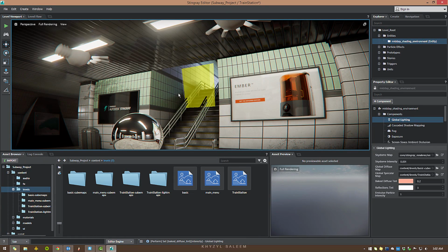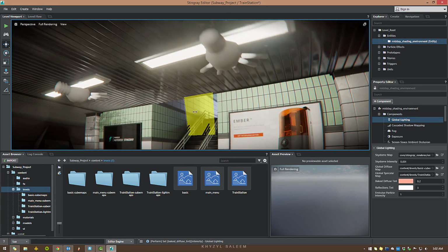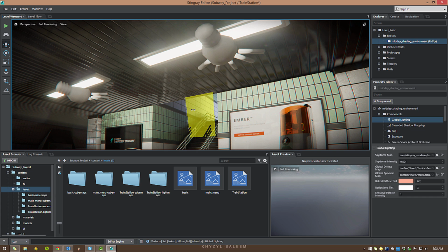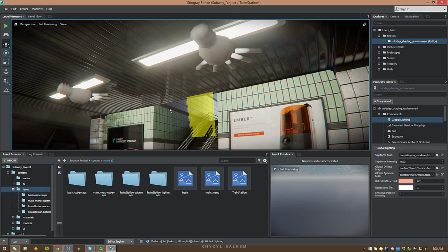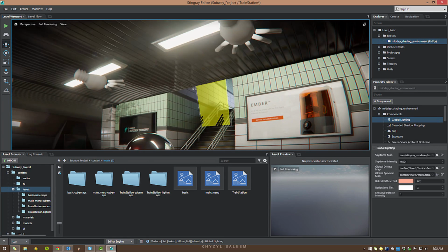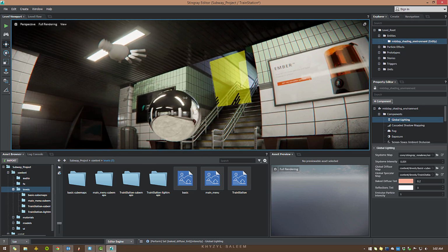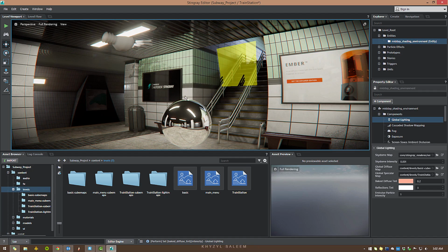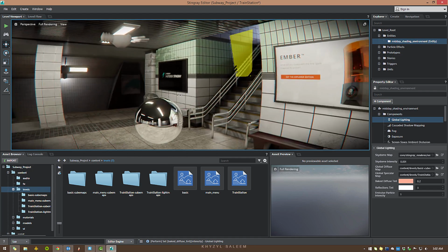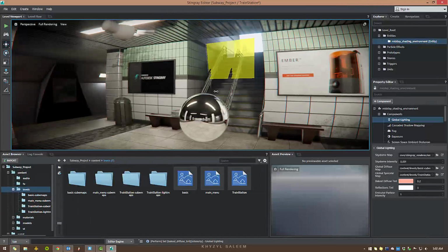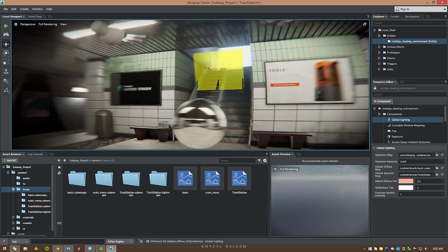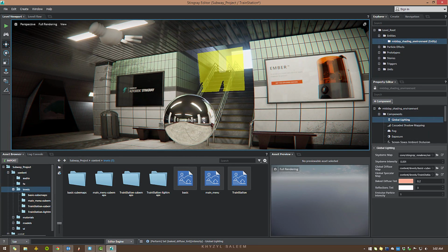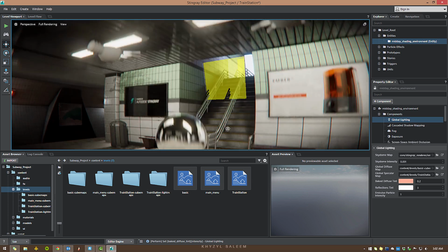The screen space reflection is real time. It runs on the GPU of the video card, and therefore it's more performance heavy, but on a good platform obviously it makes a huge difference because it's more realistic, the reflections are more accurate, and the reflections do not require texture memory because it's all done at runtime on the GPU. Whereas a cube map obviously requires a texture, so it takes up VRAM on your video card, but it doesn't have as much of an impact on the GPU, so it's cheaper to run as far as performance goes. However, if you want something more realistic, you should go with screen space reflections because the cube map reflection is not as correct, it's not as accurate.